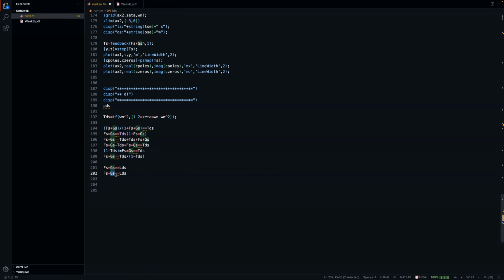And it is that GS or its inverse should be stable. So I'm going to take the inverse of the transfer function, so times GS to the power of -1, but with the restriction that GS is a stable transfer function and its inverse is also a stable transfer function. So that would mean that both the poles and the zeros should be on the left half plane, because when we invert a transfer function, poles and zeros switch places.